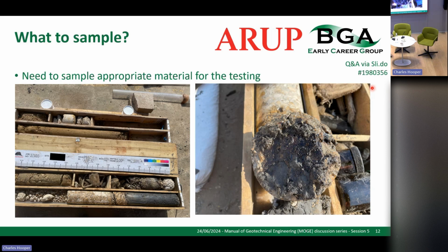In this instance, then we have to go back, we have to really look at it and work out where exactly do we want to take our samples. One of the more interesting things on this one as well is that the base of that concrete was actually impregnated with an oily sort of residue, but there was just no way that we could take a sample of it. It would just be a lump of concrete that wouldn't be an appropriate soil medium really.